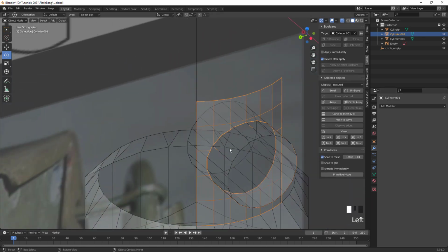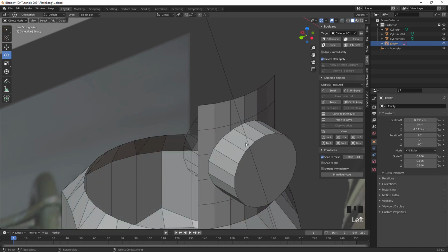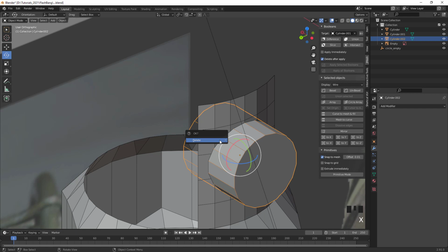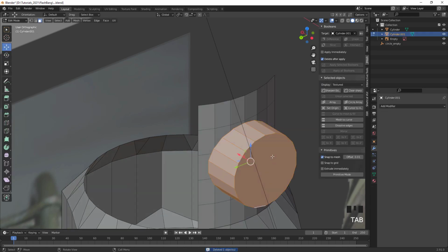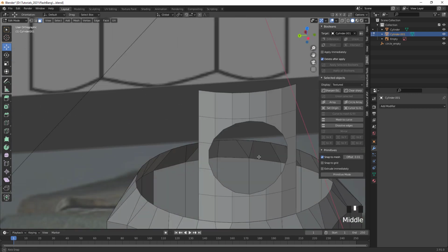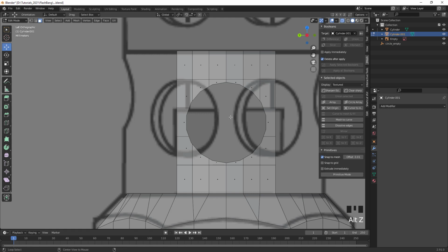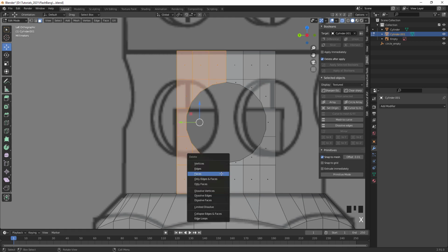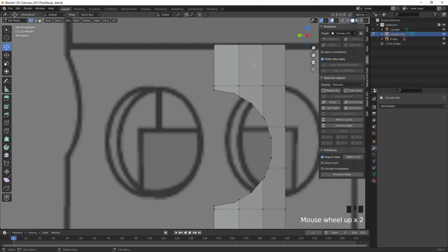We can then apply the modifier and select that object, the Boolean operator, and say X and delete. It also left that piece here for us, which I'm also going to delete. We don't need that. So now with that selection here, let's delete the left half of it. And now we can clean that up here. And later we copy it back into place with the array modifier.